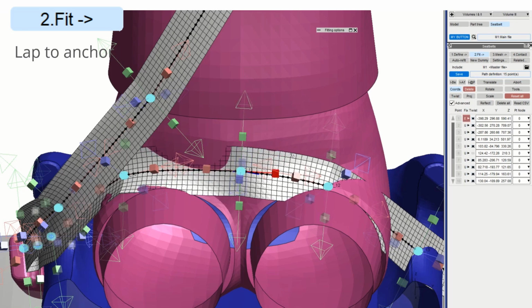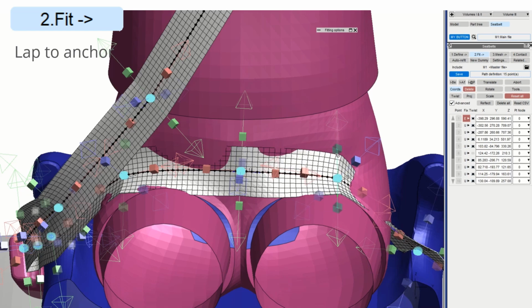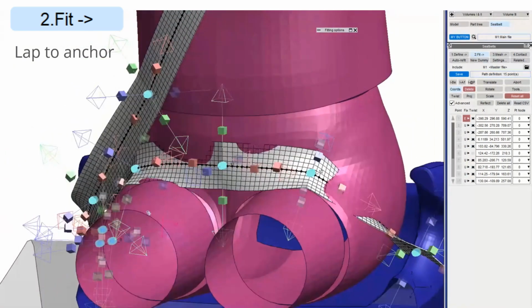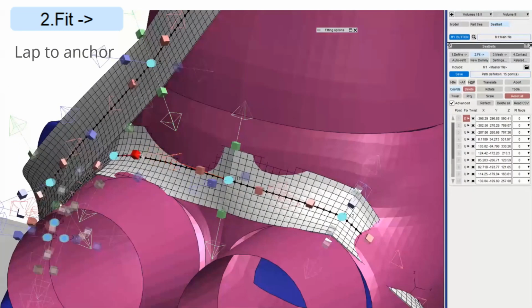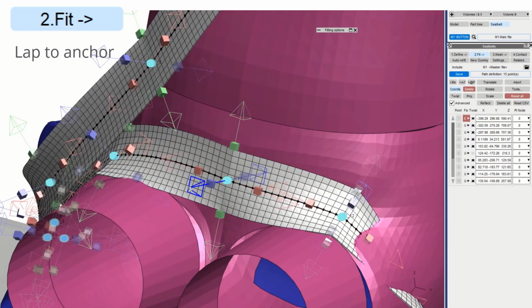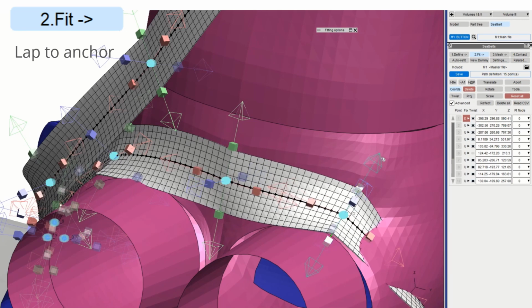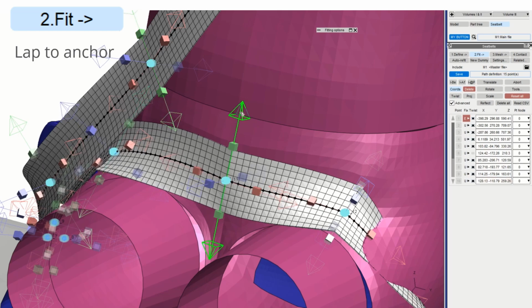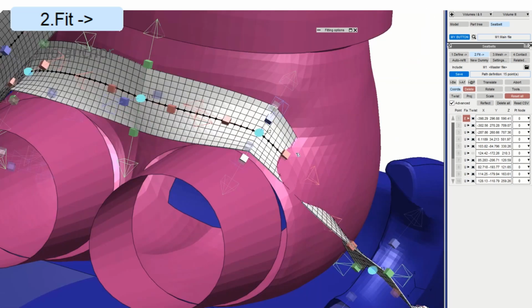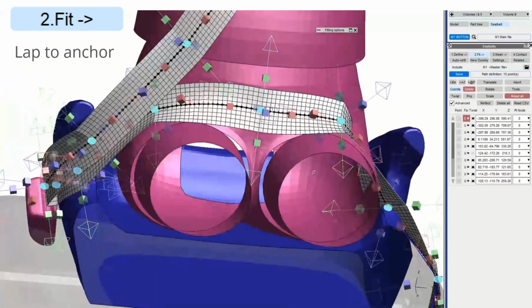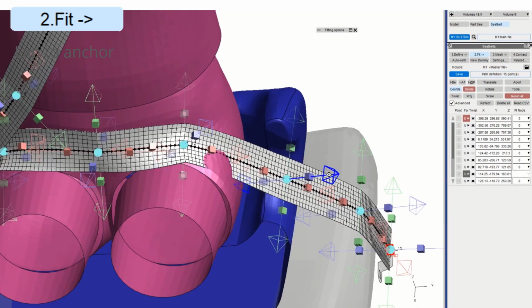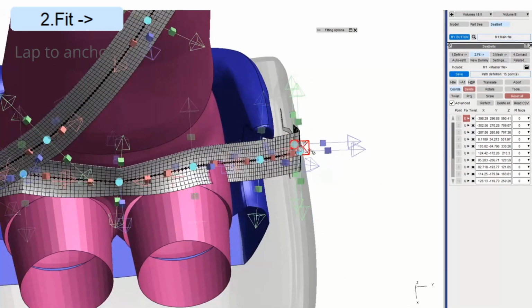The lap is always a difficult part to do because in test the adult dummies sometimes wear t-shirts and the child dummies have neoprene jackets. If you're using side impact, of course they have neoprene jackets, and that can be a significantly different location to the surface of the finite element model. And you want to try to represent the correct amount of slack in the belt system, and of course the height up the pelvis block is very critical for the correct loading on the pelvis, especially in front impact.